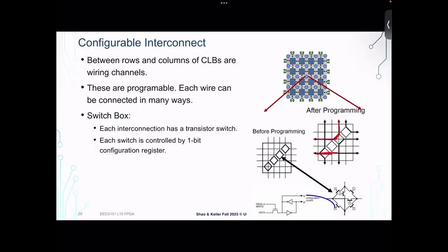And so you can start to see how you can use this to wire arbitrary CLBs together to have arbitrarily complex logic functions, combinational logic, and then state elements, flip-flops, same as you would have in a gate level ASIC design, onto the FPGA. And I say arbitrary up to some size, right? You can make a bigger and bigger design, and eventually you'll run out of CLBs on the FPGA or run out of some other resource and it won't fit. Unless you've done something wildly off base, that shouldn't be an issue for your work in the labs. But it is an issue in real applications where you have to make sure your designs will fit on an FPGA.